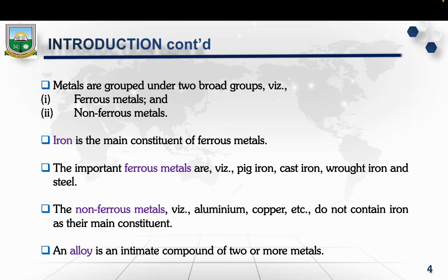For instance, in an aircraft, you can't use steel to build it because the aircraft would be very heavy, and one prized property of an aircraft is that it is supposed to be light. One metal they prefer in that situation is aluminum. The same applies to the design of a car or other automobile machines. So, try to look at a choice between steel and aluminum in a construction scenario, and imagine which one you would go for and why.